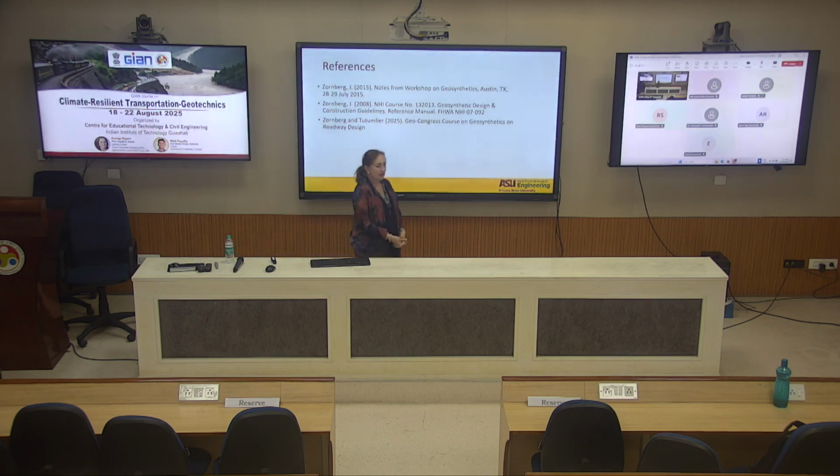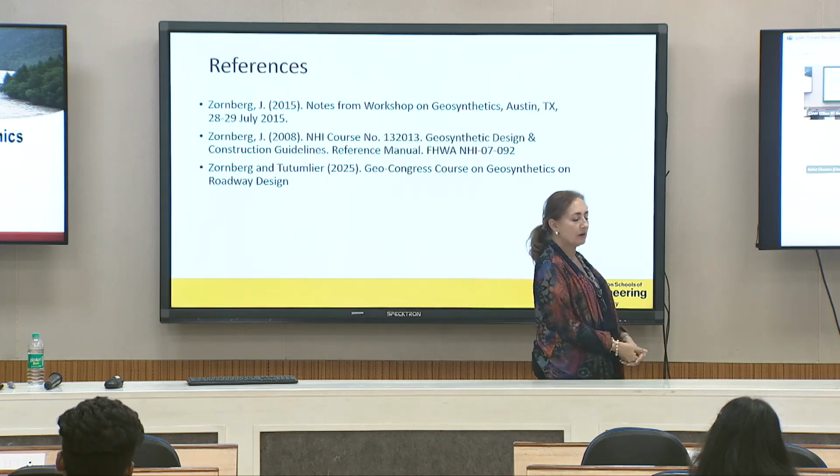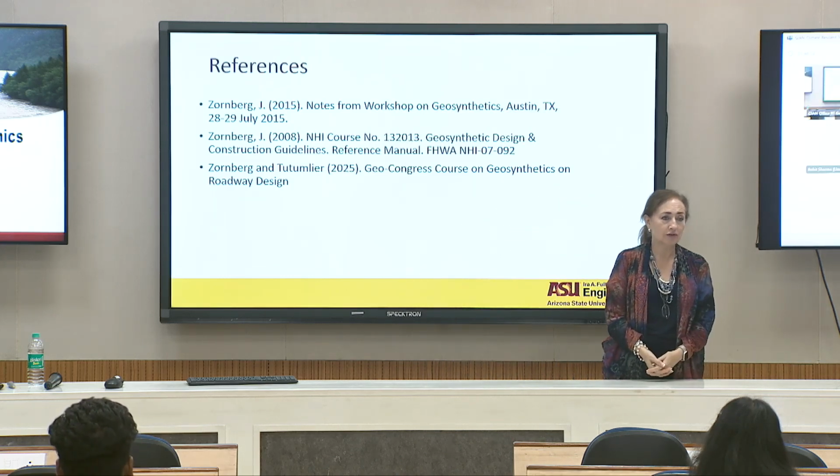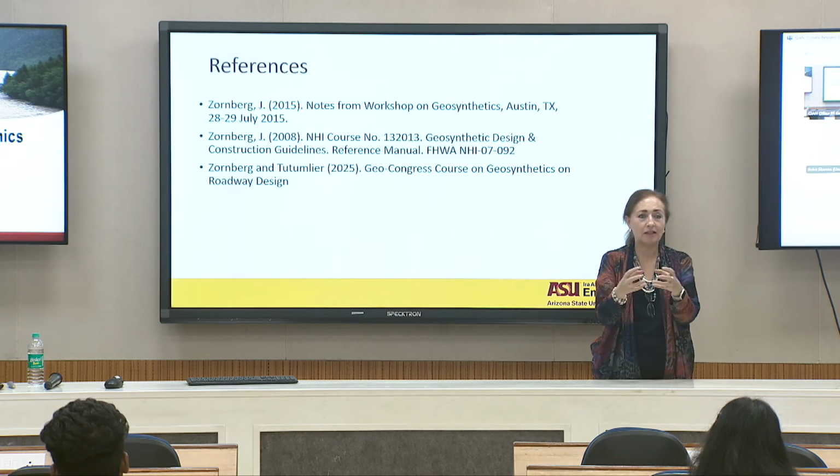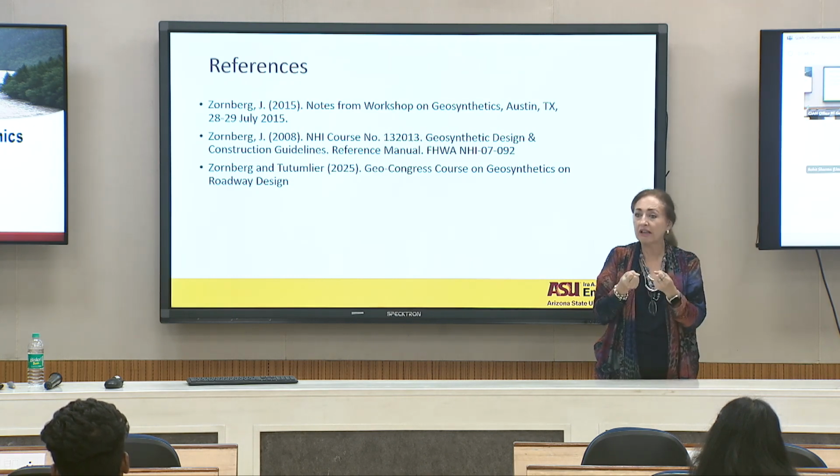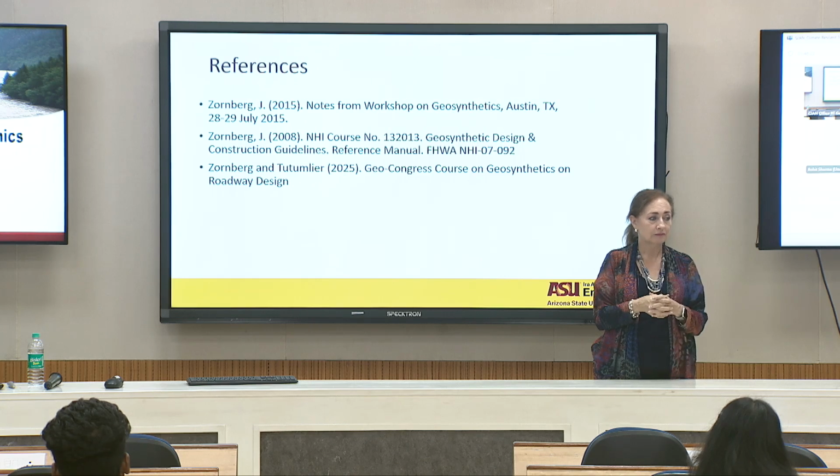the nice thing about ballast and drainage is that you do have very low suction values for ballast, right? You got granular material in there. They don't retain water. So it's good because they drain easily, right?